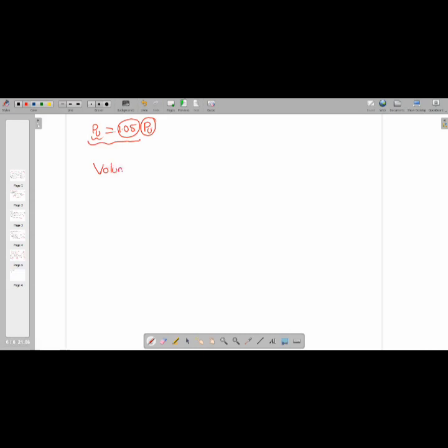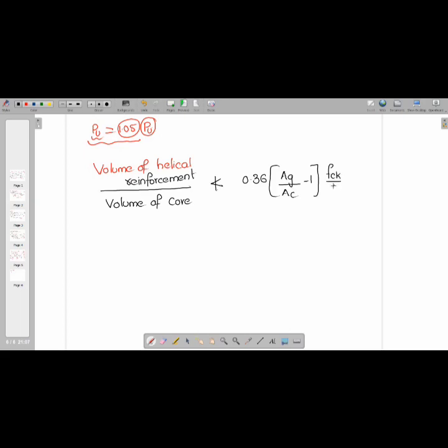That condition is: volume of helical reinforcement upon volume of core should not be less than 0.36 (Ag/Ac - 1) fck/fy. Sir, immediately again you will ask me, what is helical reinforcement, sir?